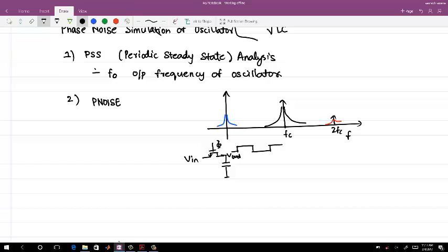So this filter you will still see as a filter, right? But then the response of this filter will be, you will have some filter response at DC plus whatever your sampling frequency is, FS, 2FS and all. Okay. Now, if I am looking from V in to V out as a low pass transfer function, I want to see what is the noise contribution of the switch resistance itself from 0 to whatever bandwidth I am looking at.